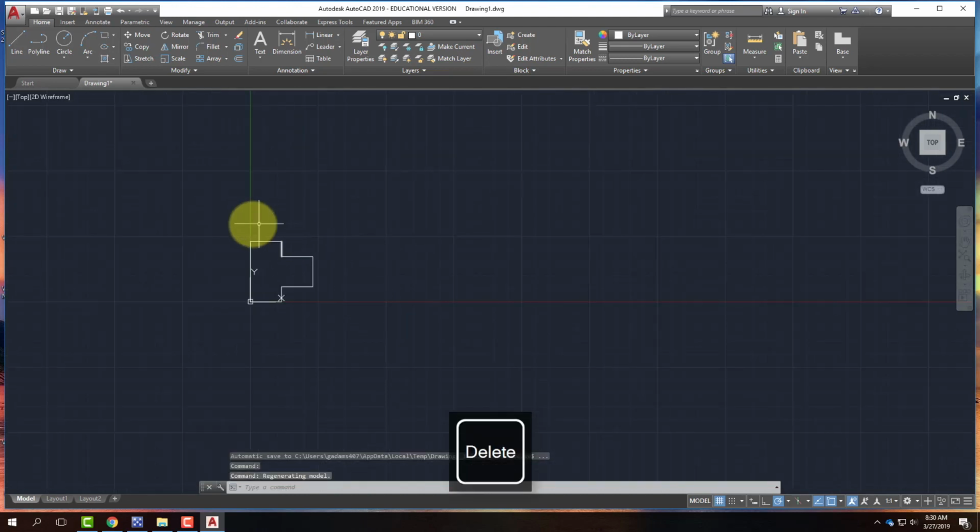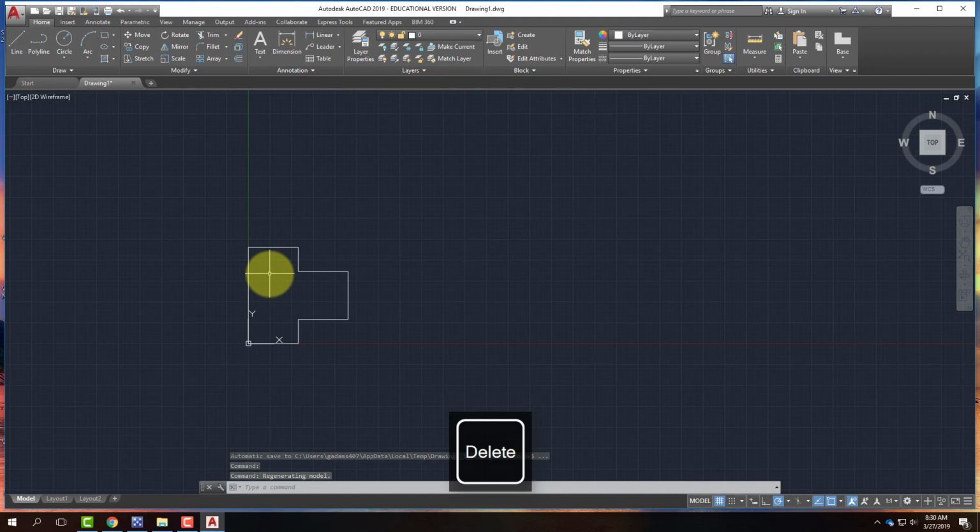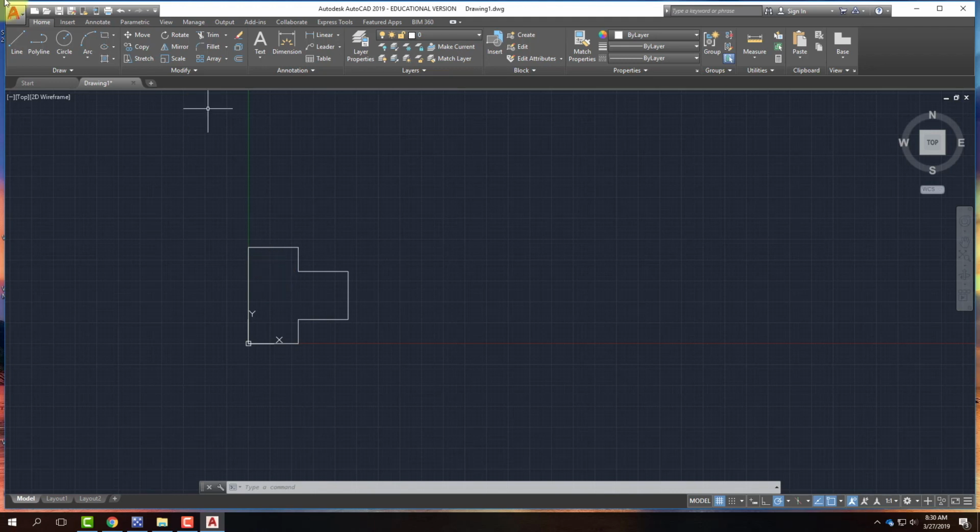So relatively easy. This is important for you to understand as a basis or an underlying understanding of how AutoCAD works. Is it the way we draw everything? No. We frequently don't use this at all. I'm going to show you the way that we use it, and that's why I had you turn dynamic input off. But if you understand that this is an underlying place, you might need to draw the slope of a roof at a 6 and 12, for example.